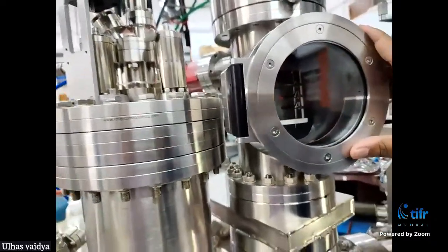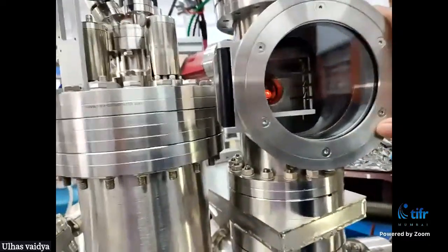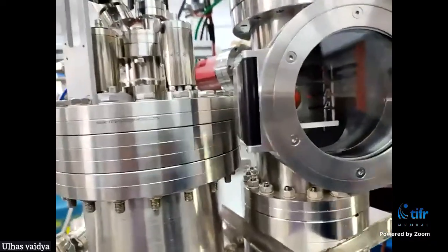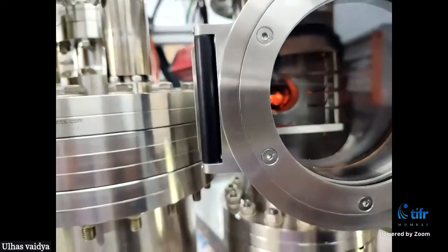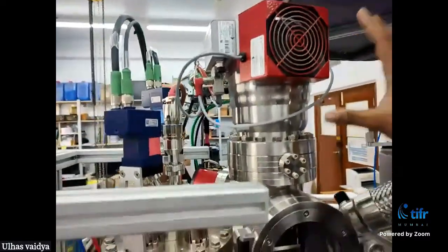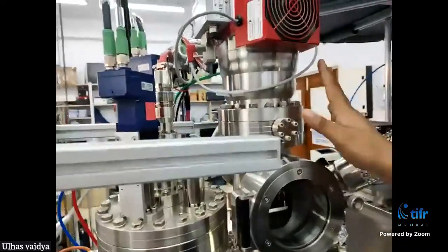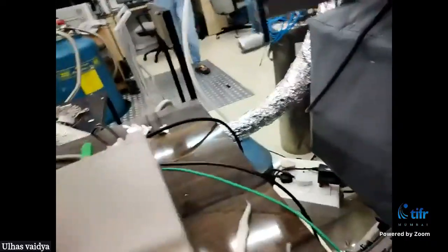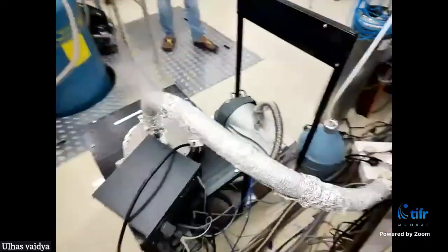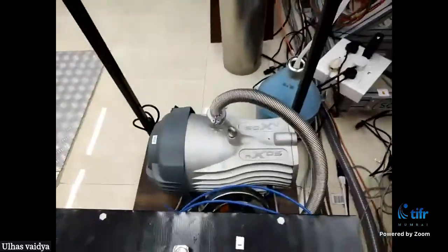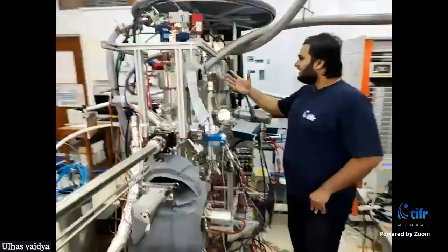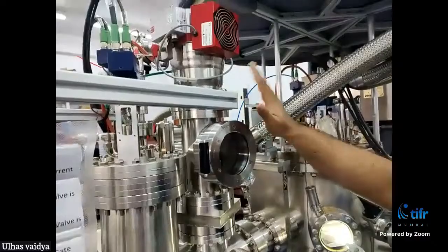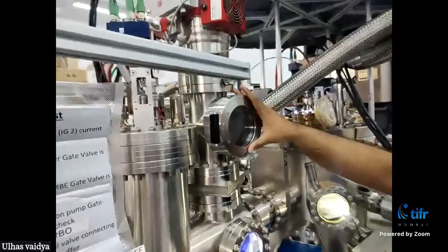Whenever you are putting in your substrate, it is put in through this chamber, and it is also taken out through the same chamber. When we put the sample in, you can see above this the turbo pump Rudra talked about, and there the scroll pump, the backing pump for the turbo. Rudra has talked about this, so I will not explain it much. We turn these pumps on after we put the sample in, and we pump it down.